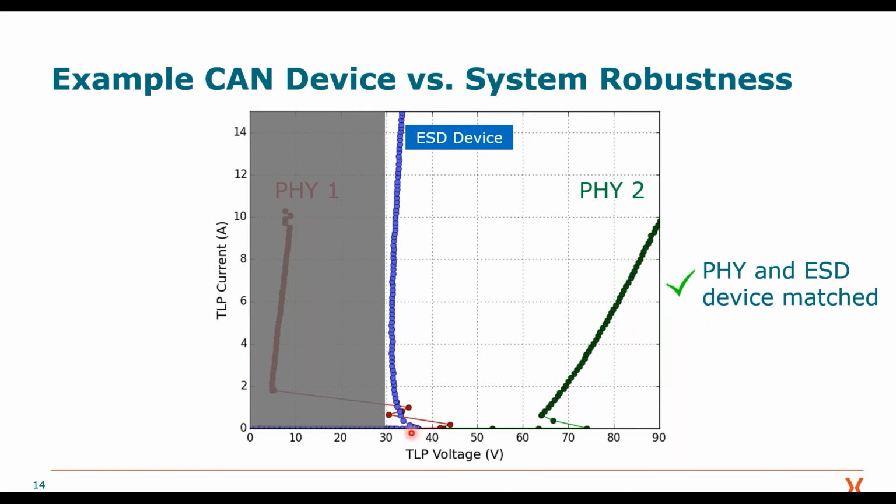The external ESD protection here is triggering first, and has the chance to take all the ESD energy. And due to the fact that it is also built to be able to take all this energy, this combination will survive the ESD test for sure.